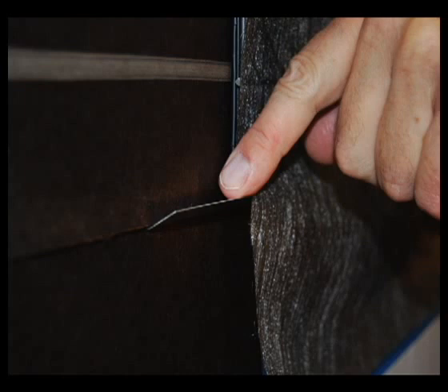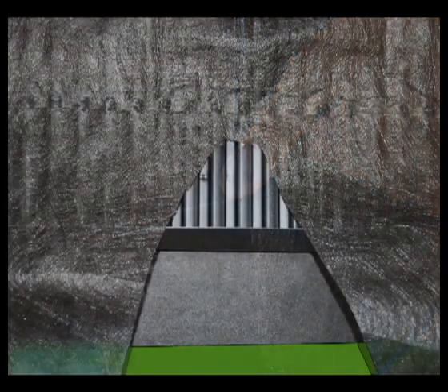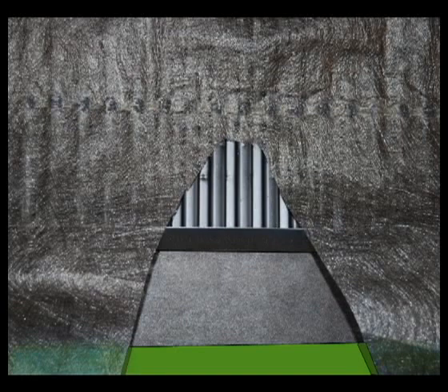Next, install the shear cavity or gravity cavity with corrugated plastic channels into the bottom of the V trough of the moisture diverter. The 4-inch fabric skirt of the shear cavity or gravity cavity wraps over the bottom flange of the moisture diverter.